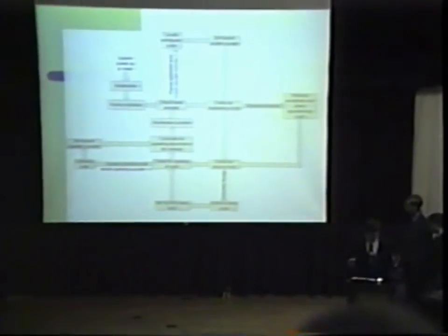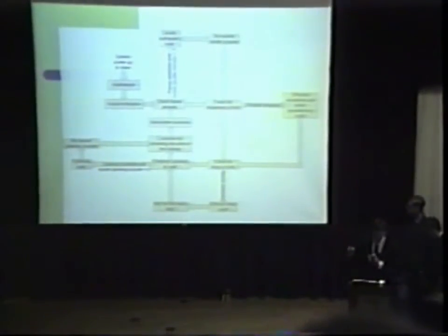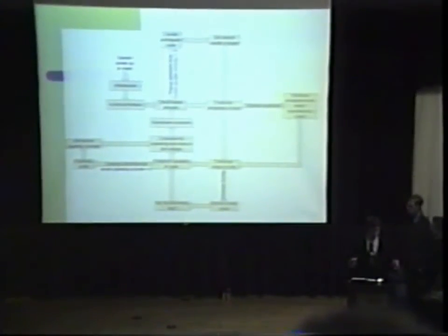Once it became above the threshold, it would then take 50 more values, and then it would check to see if 90% of these 50 values were above that threshold. If it was, then it would exit out of this loop. This ensured that ambient noise wouldn't accidentally activate our robot too soon.